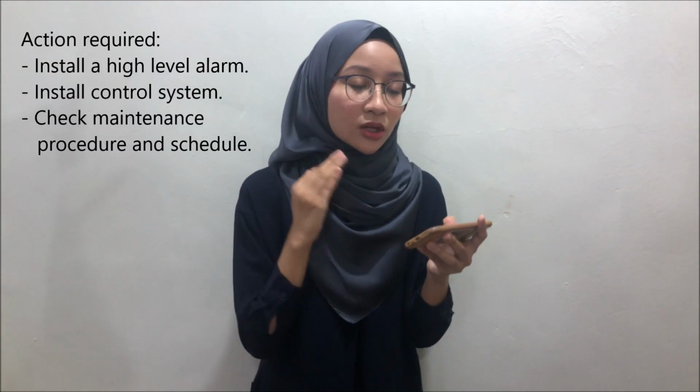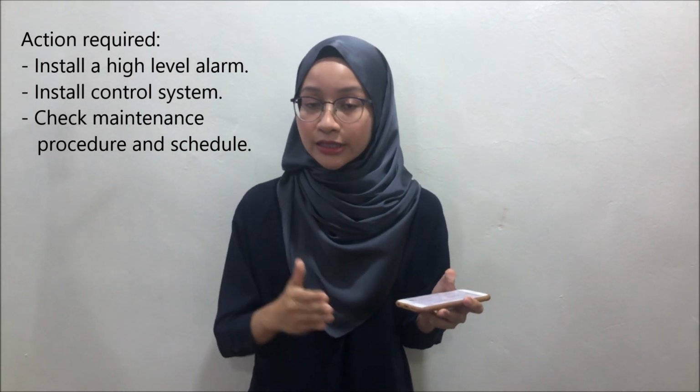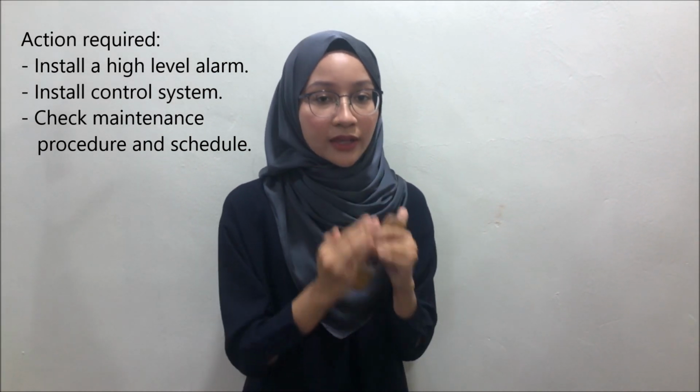We need to install a high level alarm, install a control system, and also check maintenance procedure and schedule regularly in order to prevent those from happening. Okay, for the fourth process parameter, which is the integrity. The guide word for integrity is no.